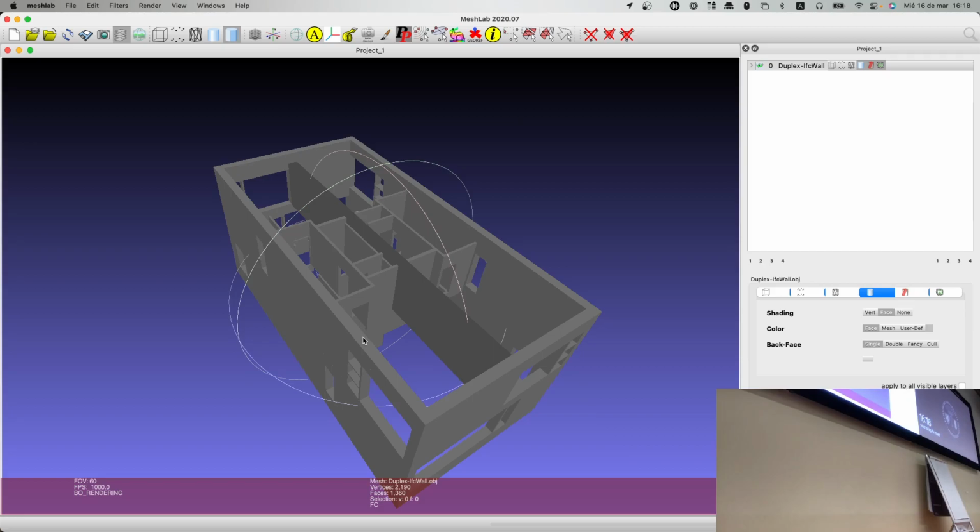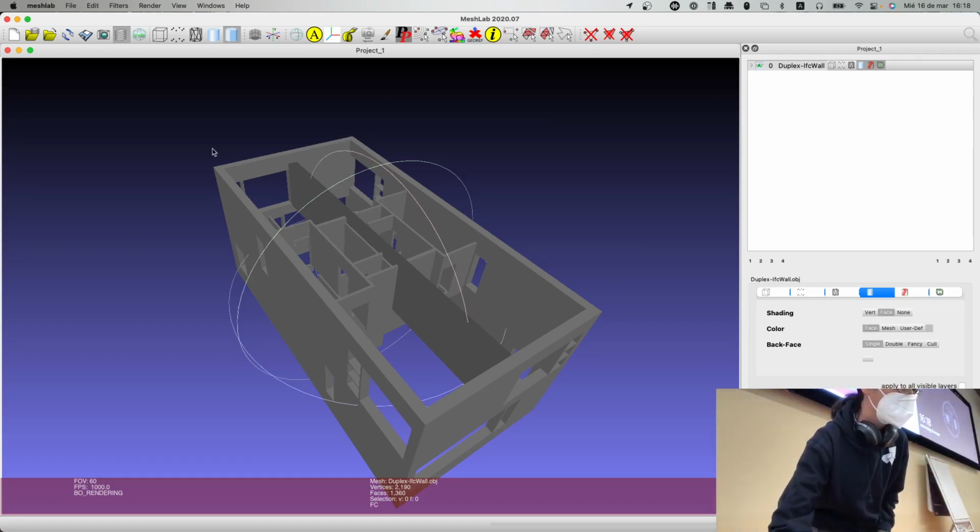Exactly which kinds of things you need depends on the model that you have chosen, because some might have ventilation ducts or something that encloses things in the top. So think of doing something like that and run IFC Convert to generate an OBJ file or maybe multiple OBJ files. And you can start from these files to run your code.